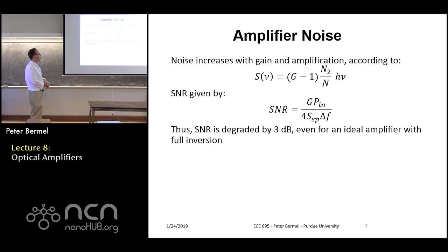And of course, if you had a very noisy amplifier, so for example, it had a lot of spontaneous emission, or there were just some crosstalk issues or something else was happening, then it could be more than 3 dB. So then that means that you need to play some additional tricks if there are a tremendous number of these links in order to keep the noise to manageable levels, right?